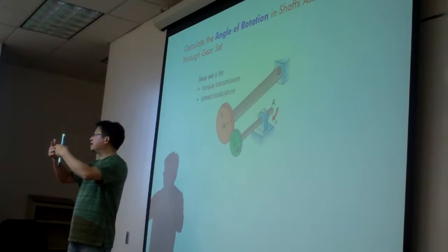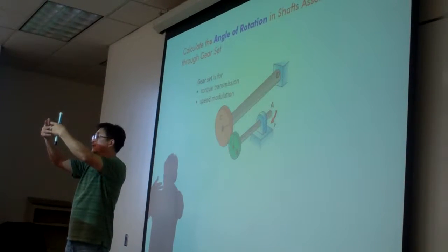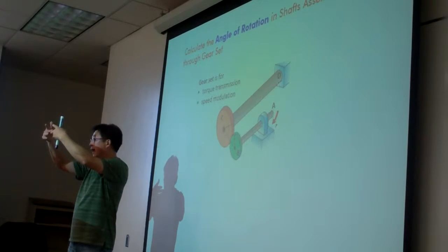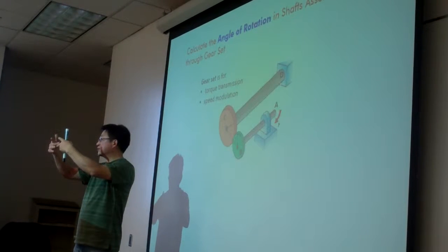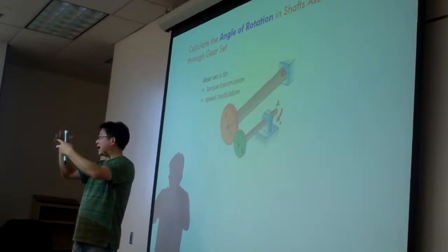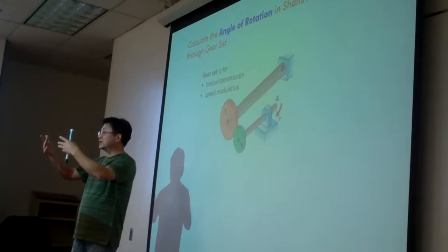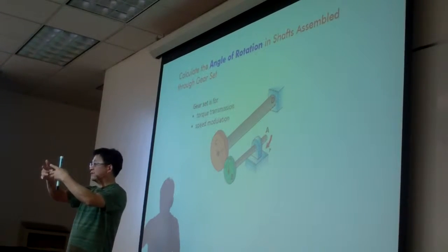If there is any noise, it indicates the pairs of teeth are sliding, which is a very bad design. The sliding or relative motion is the source of this noise, or high frequency sound. A good design transfers all the power through the normal contact force.